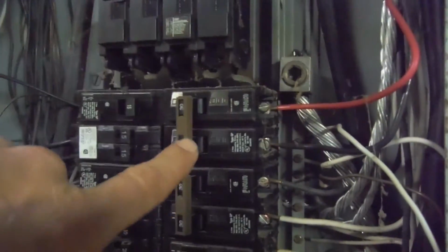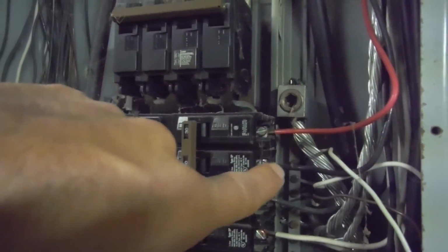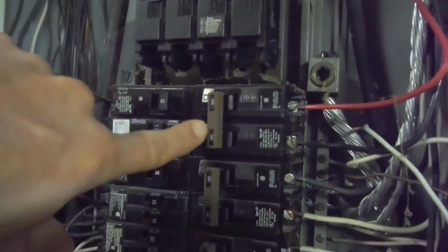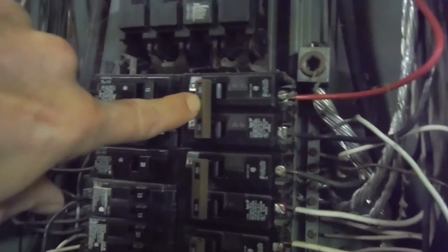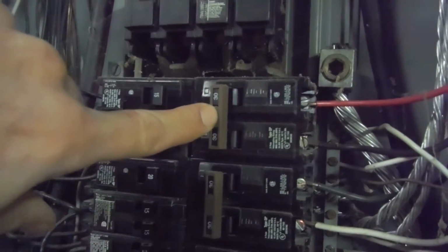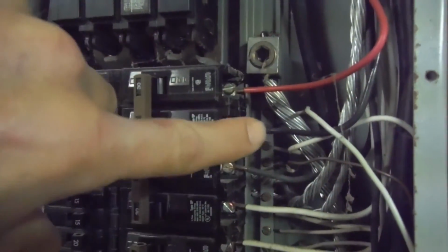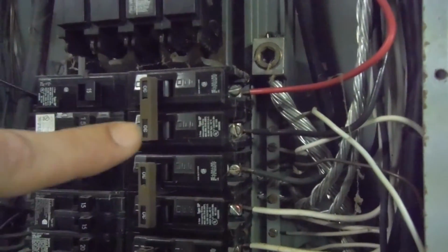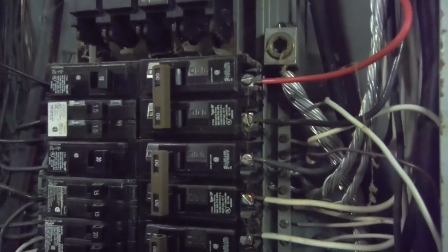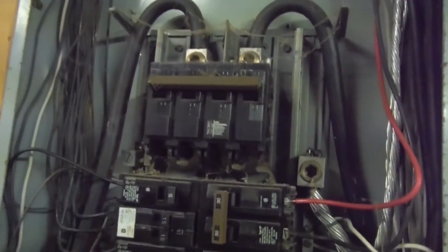Like I was saying about the offsetting of the breakers, that's where you get your hot lines right here. You get a 220 double pole, double throw breaker like right here. I believe this is 30 amp. I think that's like the stove or something like that. You got your red line and your black line. Hot and hot makes 220. 120, 120, 240. But that's pretty much as easy as it gets.